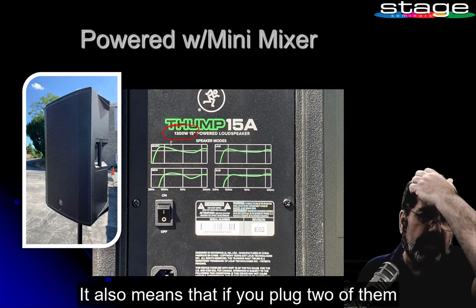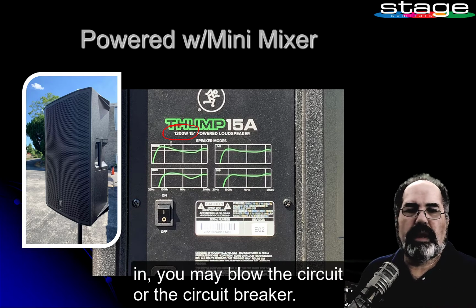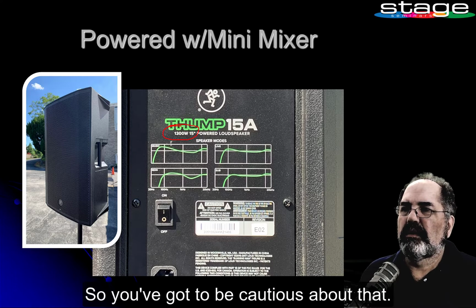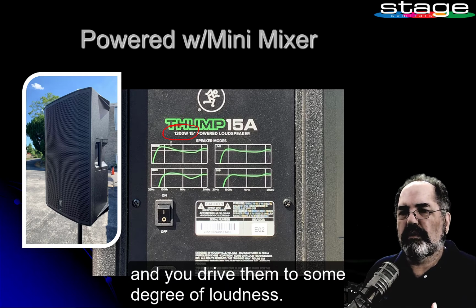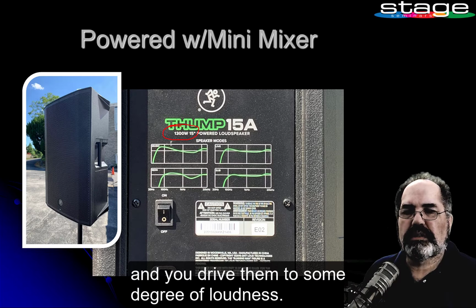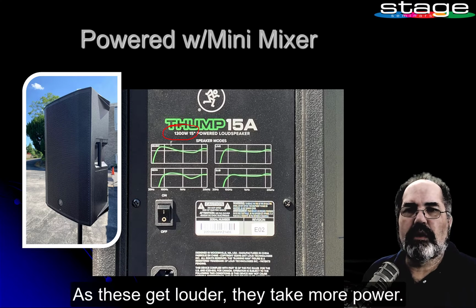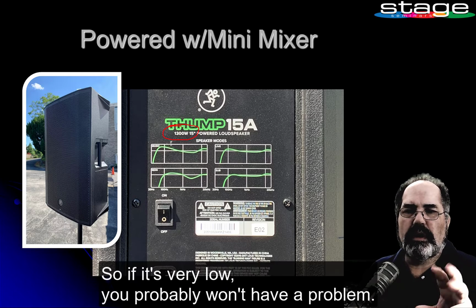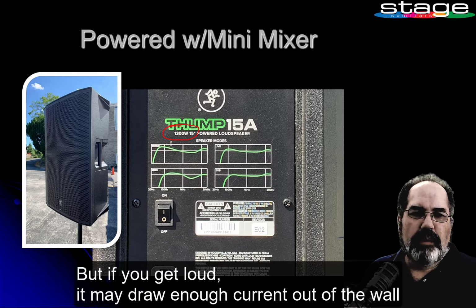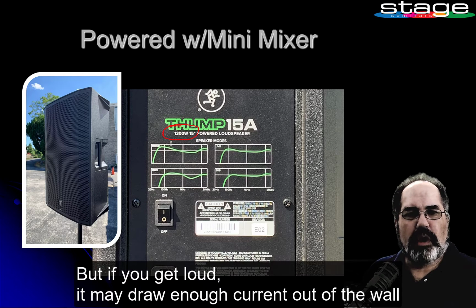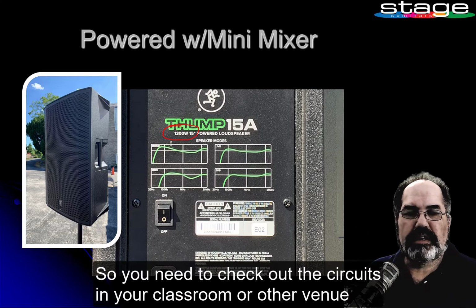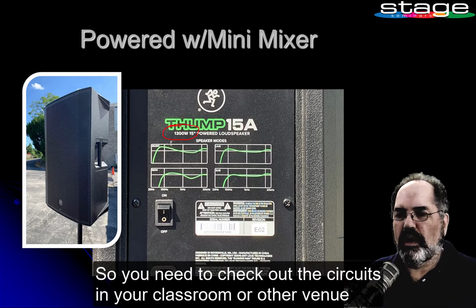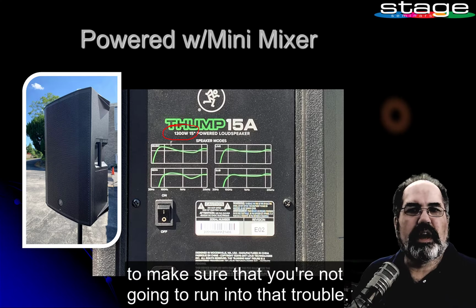It also means that if you plug two of them in, you may blow the circuit breaker. So you've got to be cautious about that. We don't want to be blowing our circuit breakers, but if you have two of these and you drive them to some degree of loudness, as these get louder, they take more power. If it's very low, you probably won't have a problem. But if you get loud, it may draw enough current out of the wall that it's going to trip the circuit breaker. So you need to check out the circuits in your classroom or other venue to make sure that you're not going to run into that trouble.